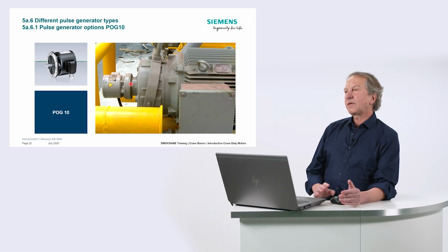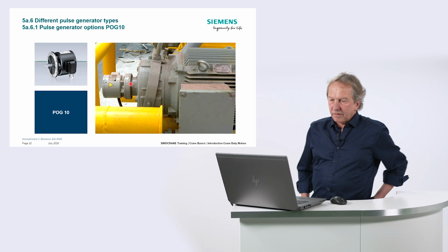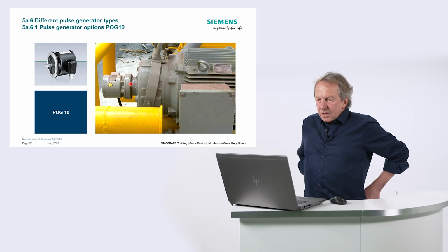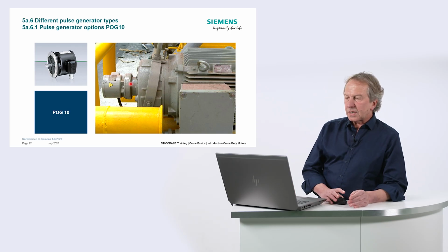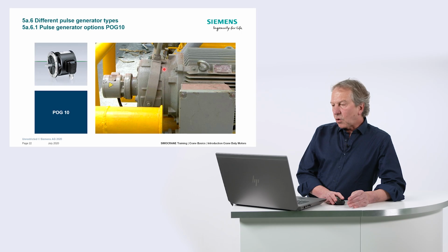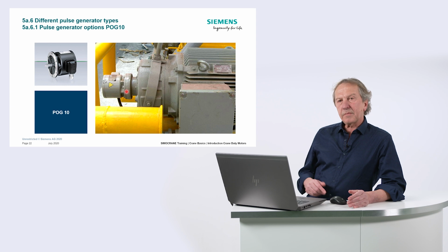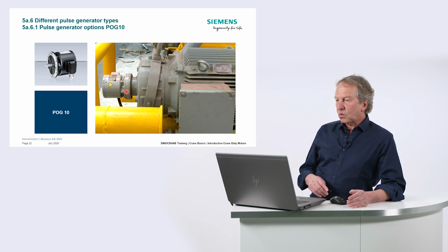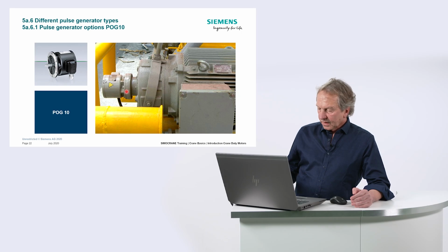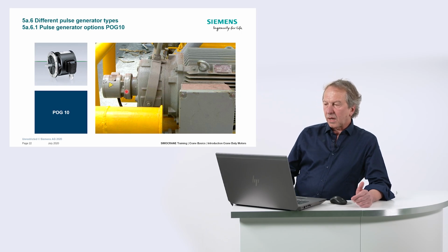Many people think if I take care and the motor is IP55, then I'm fine, but for outdoor installations, you have to have a completely closed design. I will show you later some examples where this was not considered, and this leads to lots of trouble and malfunction.